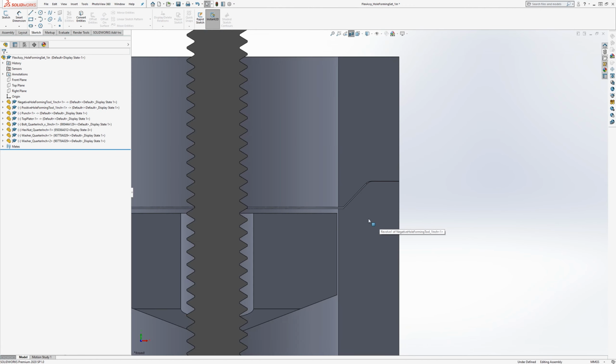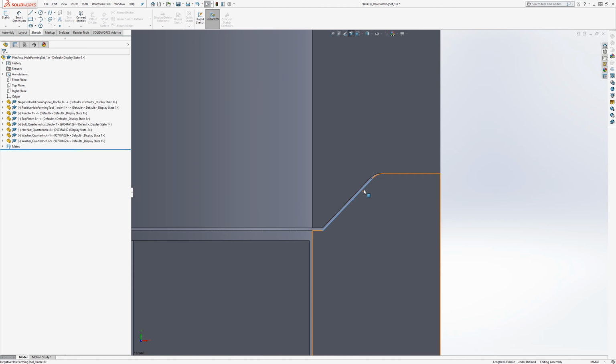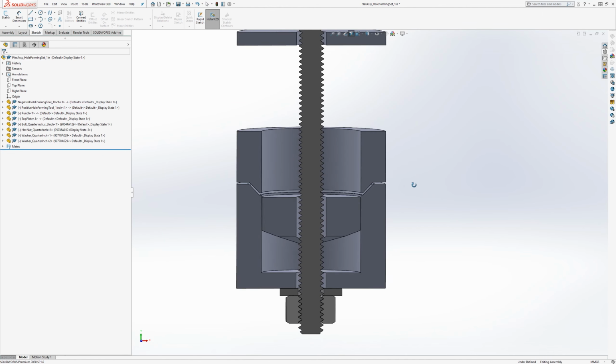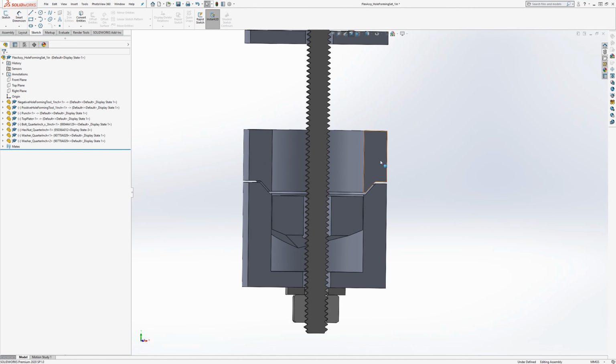So even if we design the first one, let's say we know this will be 45 degrees, something like that, and then we make a tangent curve to the flat area of where the sheet will be, we don't really want to use the exact same profile on the top one, because when it's pressed together, we need it to have a consistent gap the whole way through. So this is a good example of where we might want to use assembly geometry to define how two parts fit together in relation to each other.